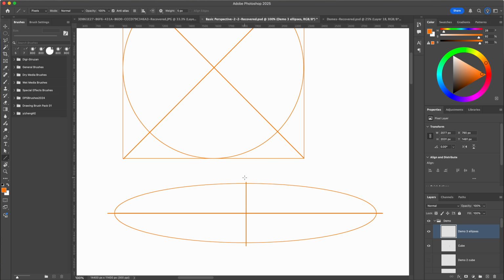Now, when doing ellipses in perspective, the minor axis is the governing thing that you need to consider the most. It has the most impact on the degree of the ellipse and how we handle these things. But that doesn't mean that the major axis doesn't have its role. It certainly does. But I have seen different sources of information say you can pretty much ignore the major axis as long as you understand the minor axis.